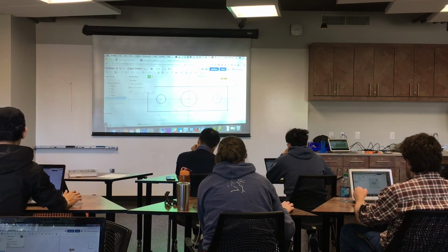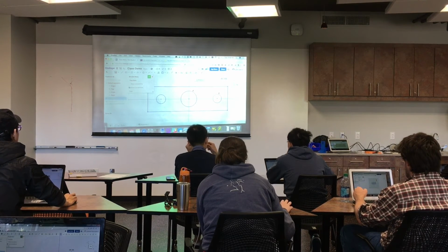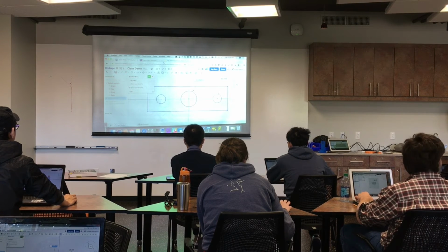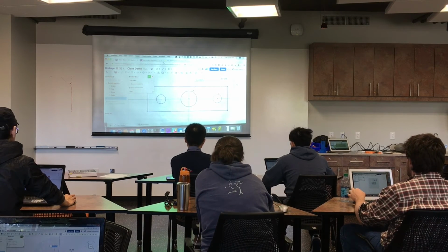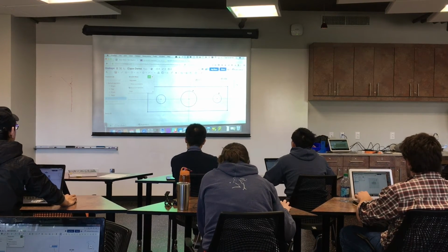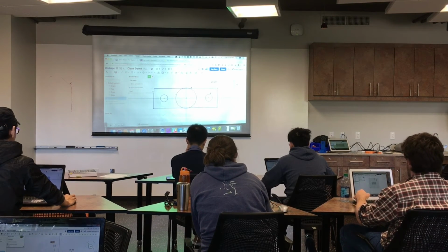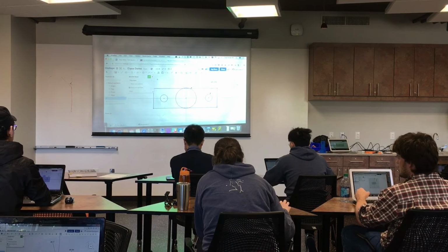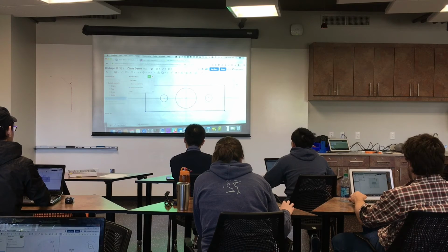We're still in the dimensioning tool. If you're not, click to get back in it. Click on this center one. Let's say that we're going to give 20 thousandths clearance to our DCDT. I know the DCDT is 3/4 of an inch in diameter, so it's 0.75. We want to add 20 thousandths clearance, so 0.77. We already see we have an issue, where this is bigger than what I dragged out. It's probably smaller than what you did, or somewhere in between. I'm going to hit escape so I can drag this a little bit bigger.